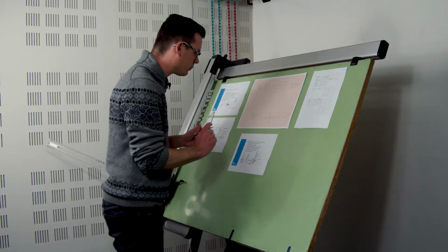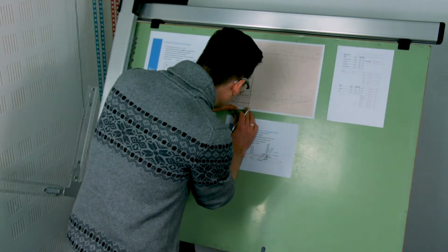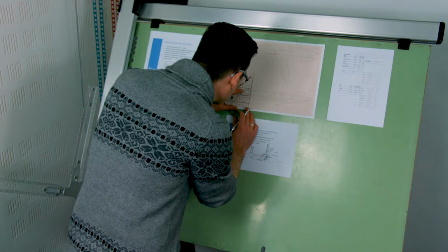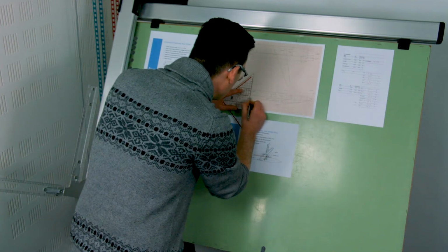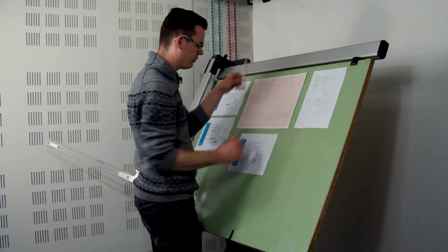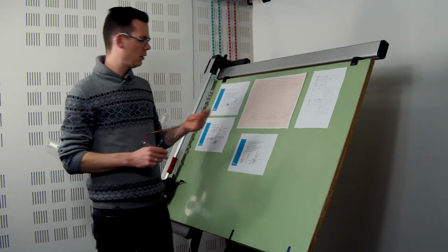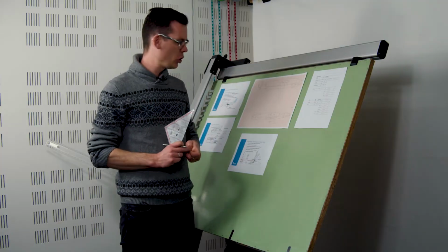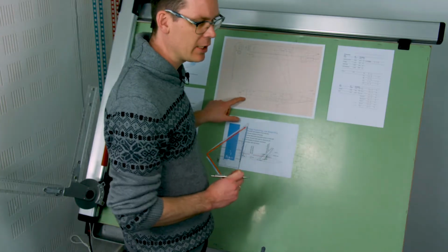Typically I can use that space to store the nose wheel. So I'm measuring this distance here to the lower side of the fuselage, a little bit more inboard, because that's where the hinge point of the nose wheel is going to be, and I'm measuring about 2.5 meters. Then I'm going forward 2.5 meters. And that indeed would put my nose wheel below the flight deck. So that is not a bad location for the nose wheel, right? So I'm iteratively checking where this nose wheel is going to end up. It's below the flight deck, which is good.